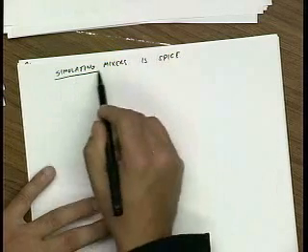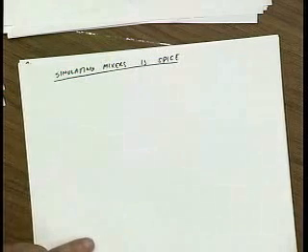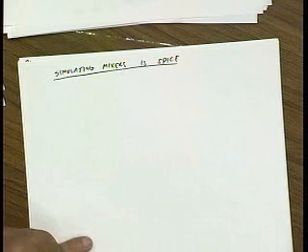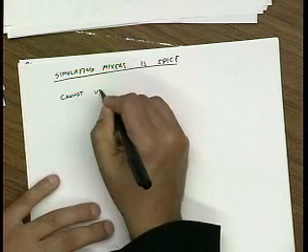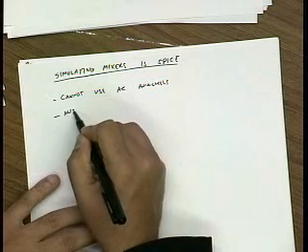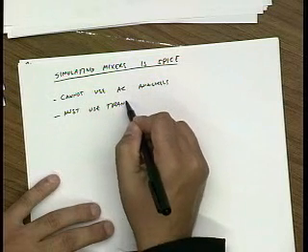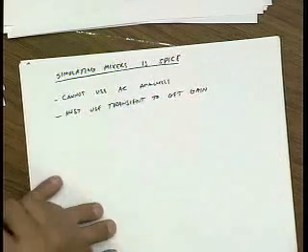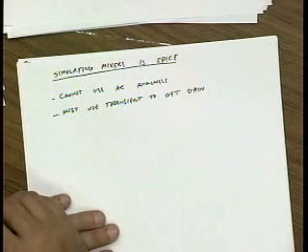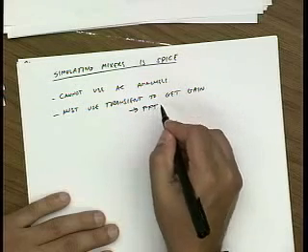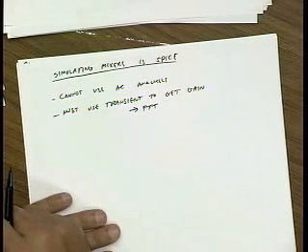And if you're using standard SPICE, you know that it's really difficult to simulate mixers. First of all, because mixers are time-varying circuits, you can't use AC analysis, right? So we cannot use AC analysis. That means you must use transient. Even just to get the gain of a circuit, you have to do a transient simulation. Then you have to do an FFT, right, after that. You have to follow it with an FFT to be able to discriminate the different frequencies at your output.